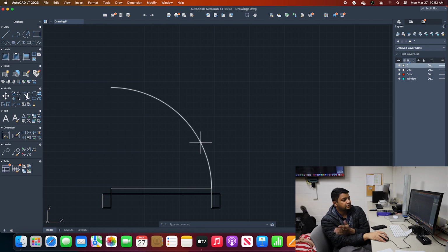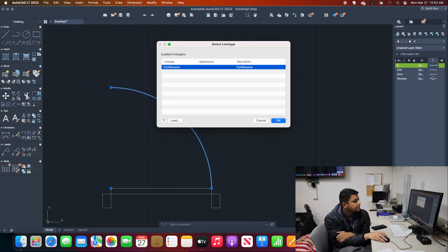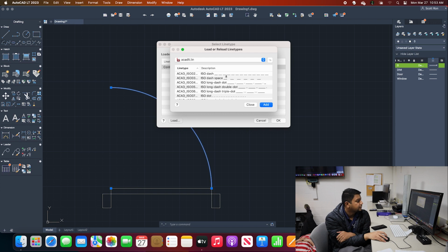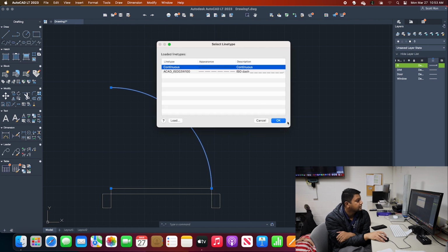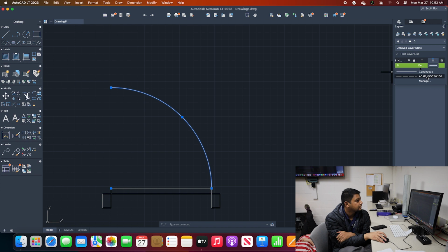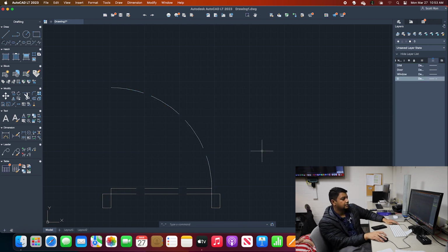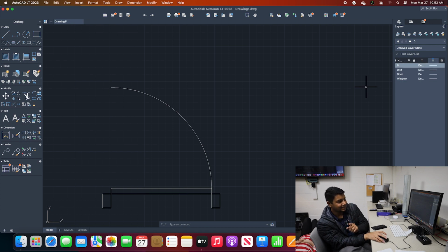So let's say Bradford asked, instead of it being a solid line, how do I make it dashed? Select the line, go to the layer that it's in, select that, and then there you go, dashed. Oh, but every line in that layer just got turned. Yeah, every line in that layer is going to turn, which is why we have multiple layers. Command Z, and we have multiple layers, and you can do that in the other layer.